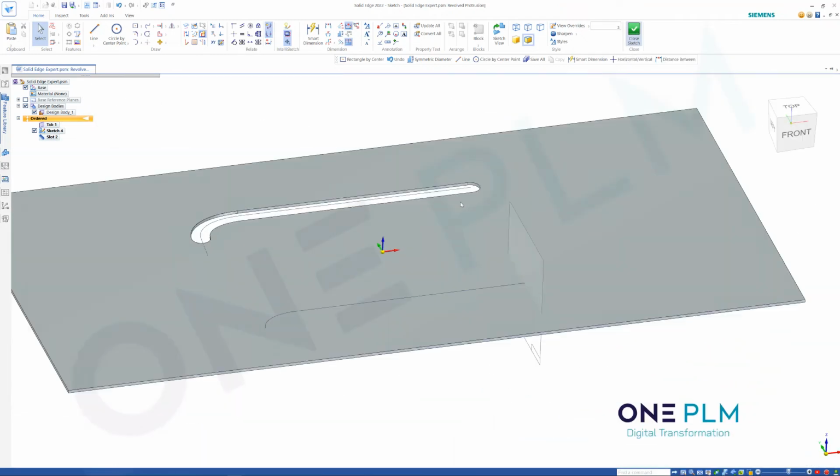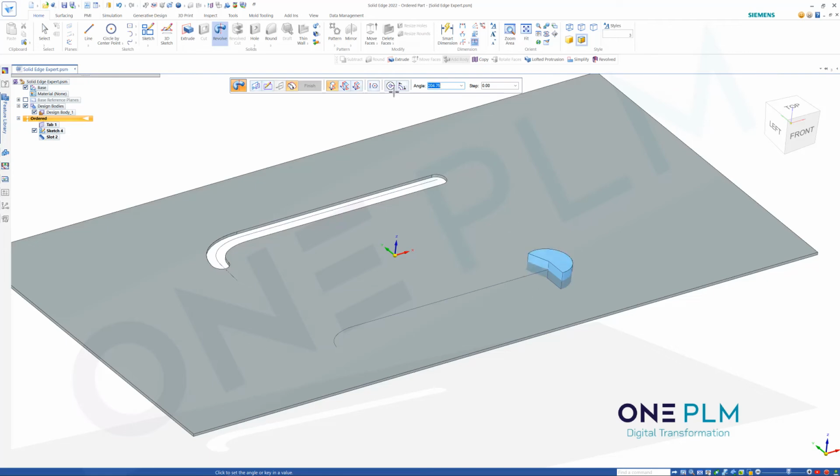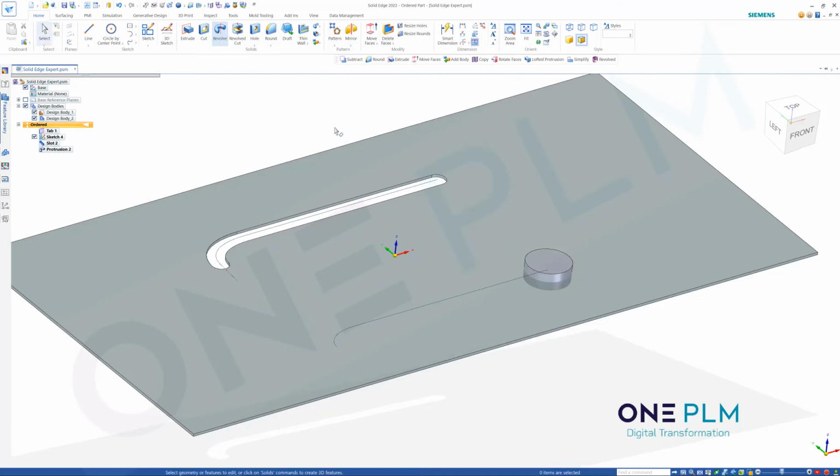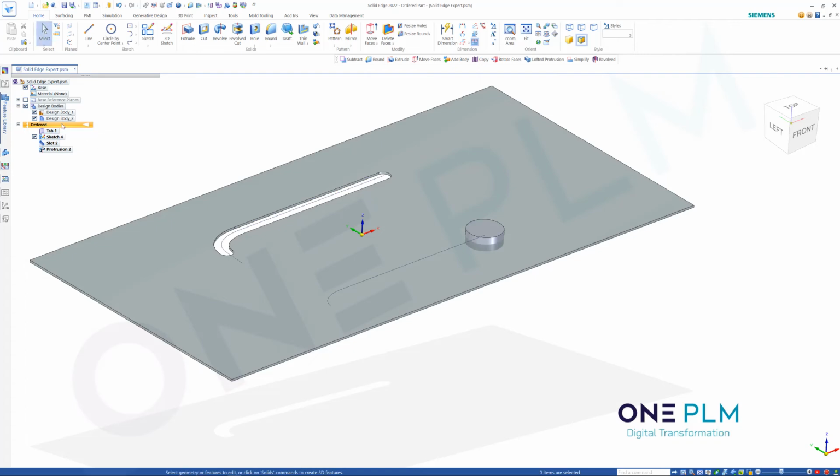So if I now close that sketch, it's going to spin back around to my original view, and then we've got several choices, but the one that we want is this revolve 360, and that has now created that as my revolve on there. So now we've got two design bodies. We've got our sheet metal and our normal one.